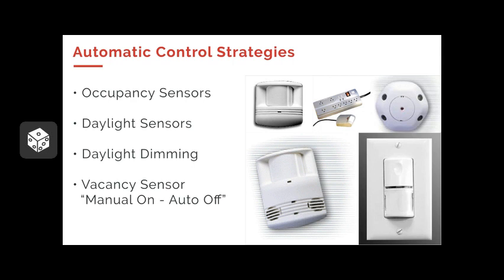There's a big difference between occupancy sensors and vacancy sensors. Occupancy sensors turn the lights on when you walk into a room, and they turn them off. You don't have a choice. I prefer vacancy sensors where when I walk into a space, I have to physically turn the lights on. I can also turn them off when I leave the space, but if I forget, they will turn off.